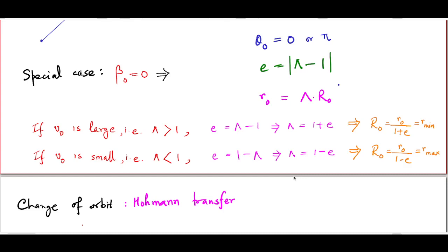Now, when such changes take place, the satellite, of course, has to fire its rockets and burn a lot of fuel. According to the standard rocket equations, which we learned when we studied motion of variable mass systems, the mass of the fuel that has to be burnt is exponentially dependent on the change in speed of the particle. The larger the change in speed of the satellite, the more fuel you have to burn. Of course, if you have to burn more fuel, you have to carry more fuel with you to begin with, which, given the limited amount of mass a satellite can accommodate, limits the amount of equipment or people it can carry.